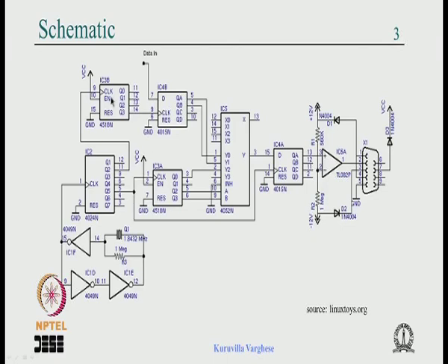If you want an inverter, you put the inverter symbol, which is marked as a part of the IC. Maybe there are 4 or 6 inverters in an IC, so it will be IC 1A, 1B, 1C, 1D, 1E, like that the numbering goes. And the pin numbers, you can see the output is pin number 15, pin number 14 and all that. People would put symbols and interconnect them with wires. So that was basically schematic capture.